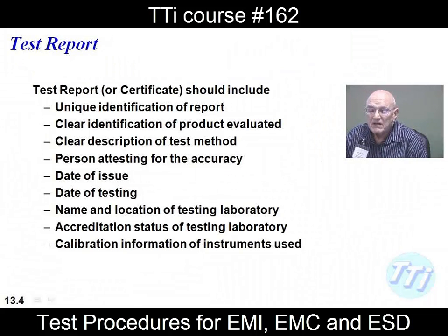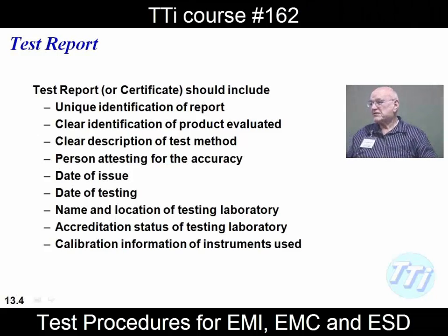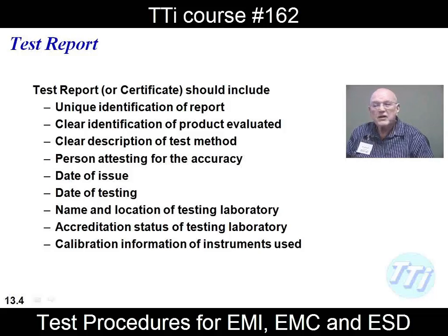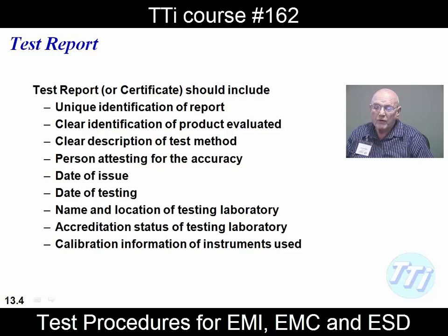Okay? Date of issuing. Date of testing. You know, the issuing, the accuracy and things like that. The actual date or dates would be more appropriate rather than just saying we started on this date, but we started and we continued. If you have multiple days going over that, you need to document those aspects of it. It's very important that you do that. And of course, name and location of the testing laboratory.